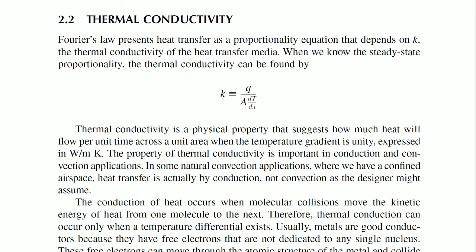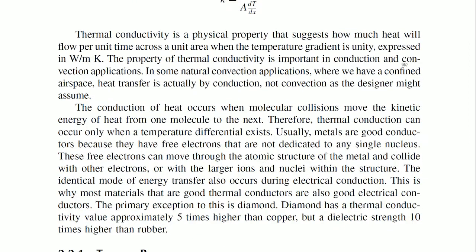Now coming back, Fourier's law presents heat transfer as a proportionality equation. With steady state proportionality, thermal conductivity K can be found from the relation here. The property of thermal conductivity is important in conduction and convection. In some natural convection applications where we have a confined airspace, heat transfer is actually by conduction, not convection as a designer may assume.